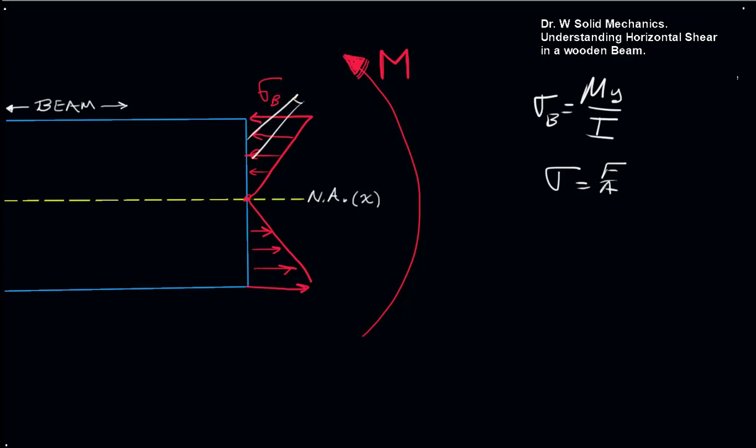So for a given cross-section of area here, this also represents force as stress times area along the beam. So we could also think of this as a force profile, where here we have compression along the top and we're in tension along the bottom.